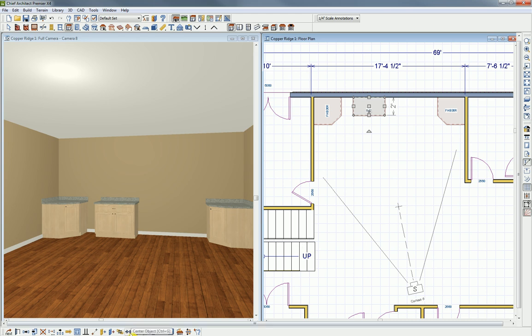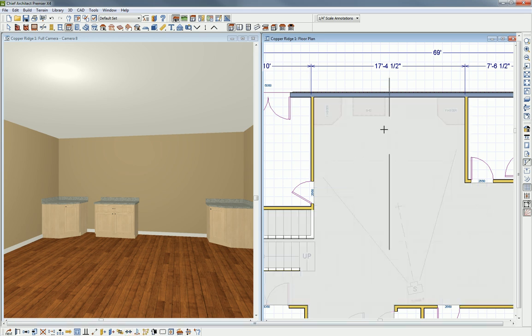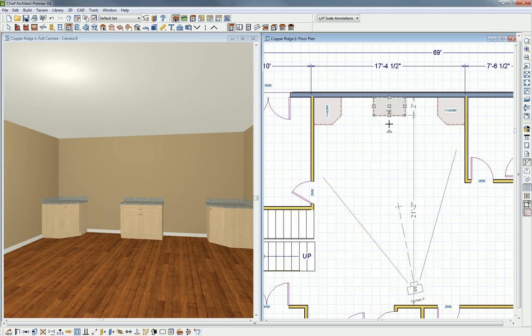Now I can go into our center tool. Those work for our cabinets as well. And we can go in and center that cabinet right on this wall. So we're sure that we're going to get that in place exactly where it should be. And then now I'm going to design the rest of my cabinets around what I've now placed, because it's basically allowing me to take into account my interior dimension here from sheetrock to sheetrock.